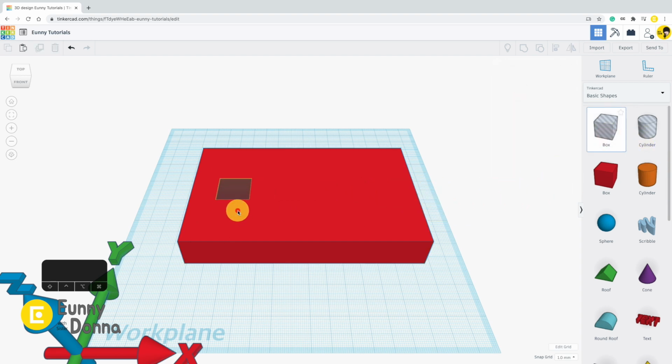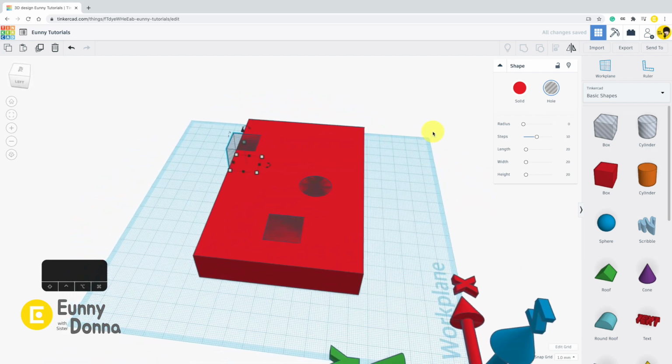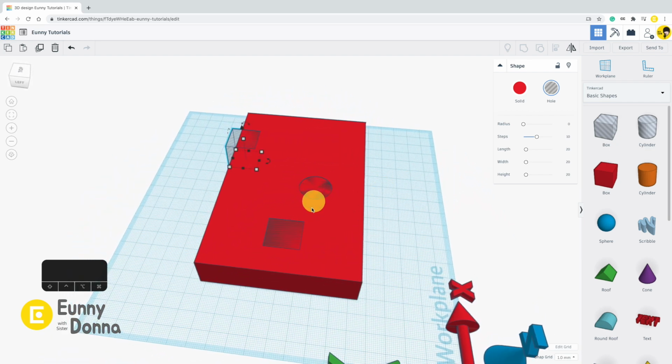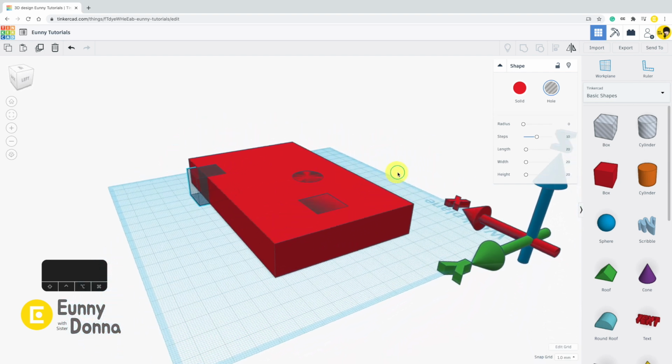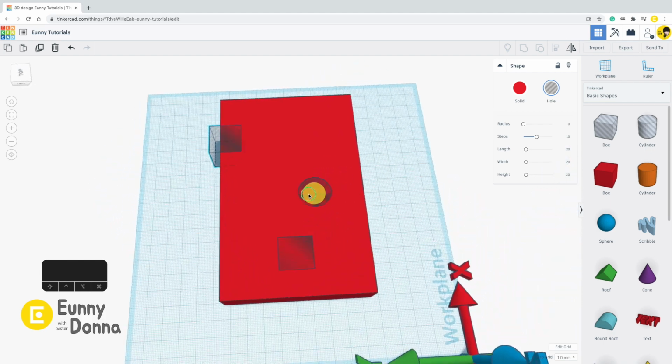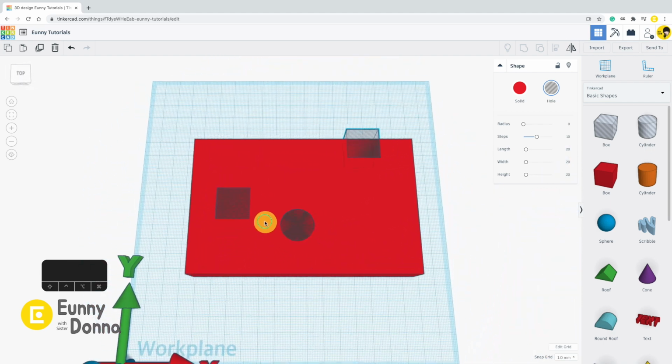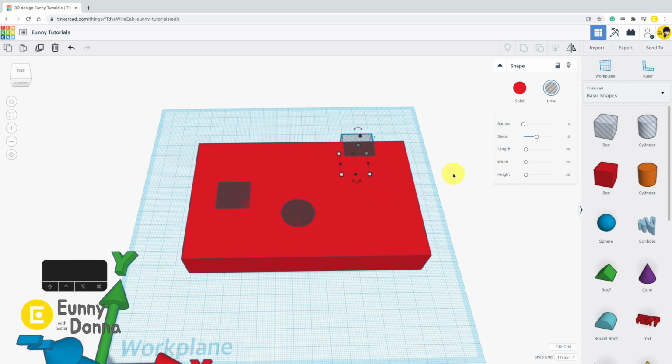If you bring the first shapes on the work plane, you can notice these are transparent with diagonal patterns. It's blinking on the top of the shapes because they have the same heights. This transparent shape is called a hole shape, which has a subtract function. The hole shape makes the overlap part subtracted. It would be more convenient to make hole shapes higher than others and locate them visibly.